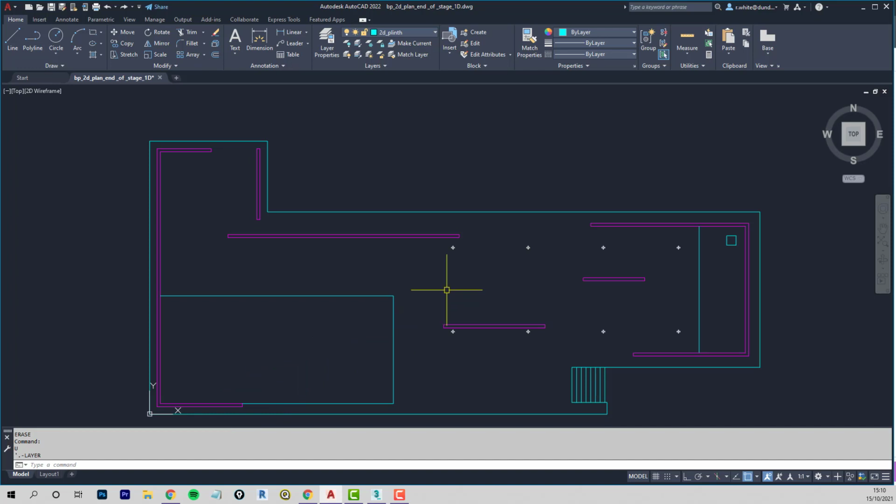Then we're looking at creating a grid to house the columns. The grid is a different line type because it doesn't really exist. If you go to the building, you can't see these lines. They're non-existent. They are just diagrammatic for the production of the building. So we use different line types for things that are underneath the ground or underneath this plinth, and a different line type for what's above our head, the shapes of the roofs above us.